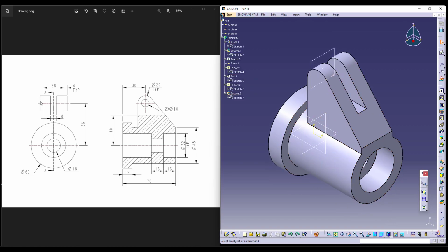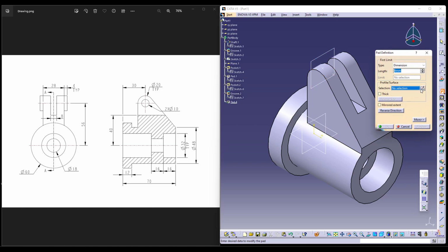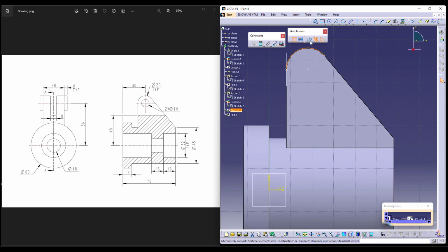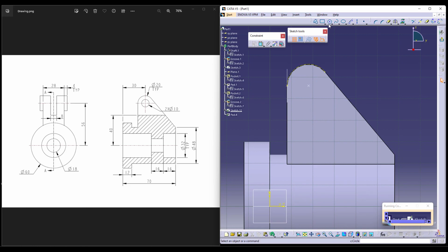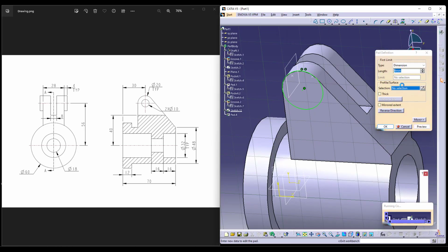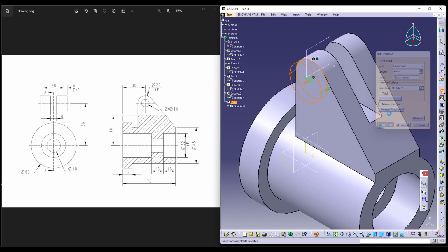Okay. Continuing after the groove cut, we have small addition of material over here which is given as 4 TYP. So let's try to add that by using your pad and then take any of our references as the sketch plane. We can use this as well. Now let's try to make a circle and then add the material. It has to maintain concentricity. It has auto taken that for me. So once I exit, it adds up to 4 mm, which we have already given.